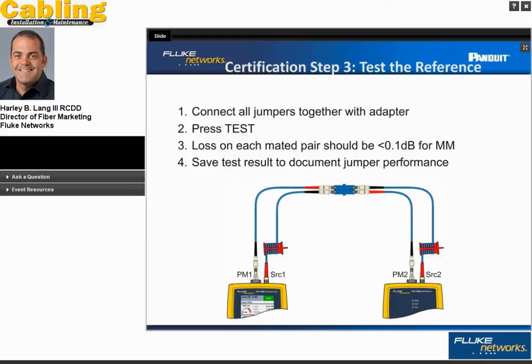There are a lot of cords out there, with varying levels of quality. A low-cost patch cord that could be used in a cabling system is not usually adequate for doing certification work. It's not adequate as a test reference cord. If you're not using a test reference cord that came with a tester, you can test it pretty easily. Once you set a reference, you can insert it, as the diagram here on the screen shows.